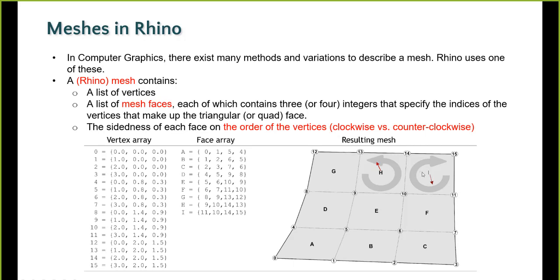One can actually point inside, since these are all individually determined by this list. That can be problematic, and you typically don't want to switch directions of the faces in the middle of a mesh. So we'll stick to the convention of always using counterclockwise. That's a very efficient way of storing geometry, because there are really just two lists of information: one list shows the geometry, and the other represents the topology, right?